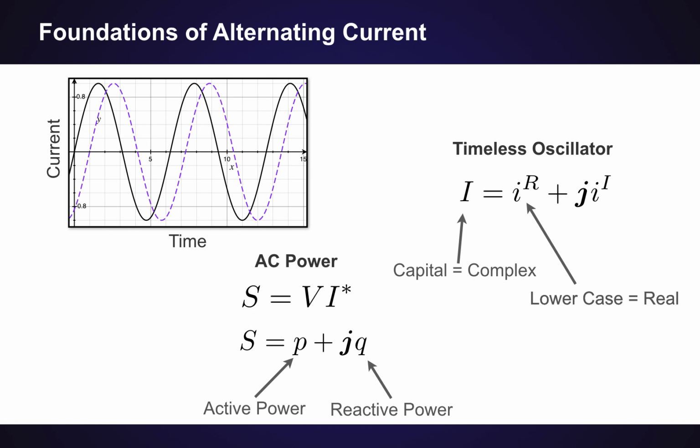It is important here to remember that when we have equations like we have here for S as a function of V and I, we really have two equations, because we have the equation for active power and reactive power put together in one. I think it's also worth noting at this point that in power system textbooks, both the complex form and its real parts have special names for almost every interesting quantity that you might want to measure.